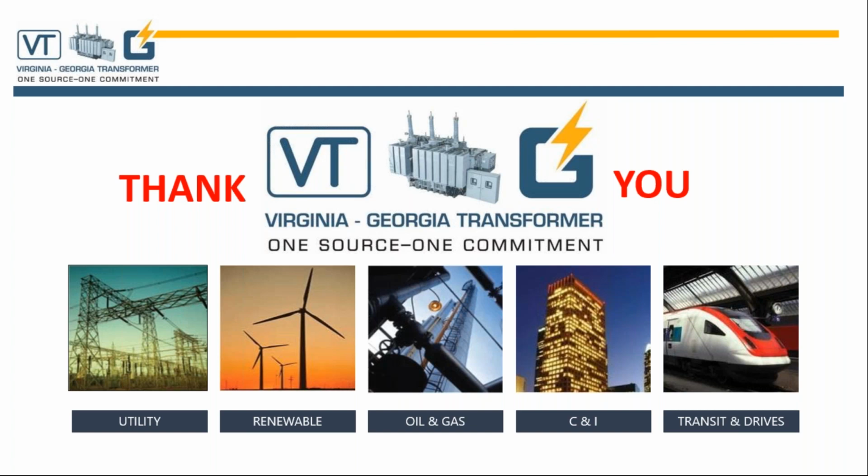I think this goes back to, does this add to overvoltage issues? Would a tertiary winding help? Go ahead, Paolo. A tertiary winding is a delta connected winding which solves the problem when you have a Y connected unit: you need to add a tertiary winding for third harmonics to flow. And in the US, especially if you have HV and LV both Y, we don't build without a delta connected tertiary. Yep. And it is maybe only done for small ratings of 1-2 MVA, but this will only solve the problem of zero sequence.